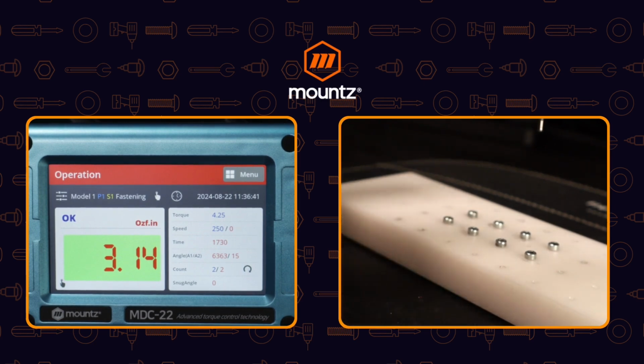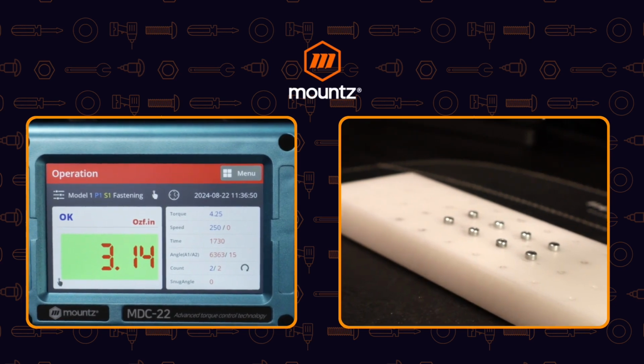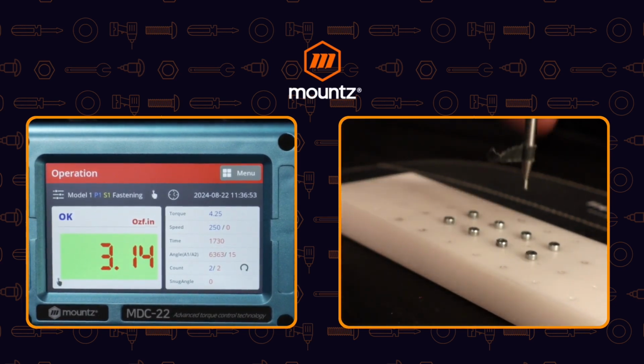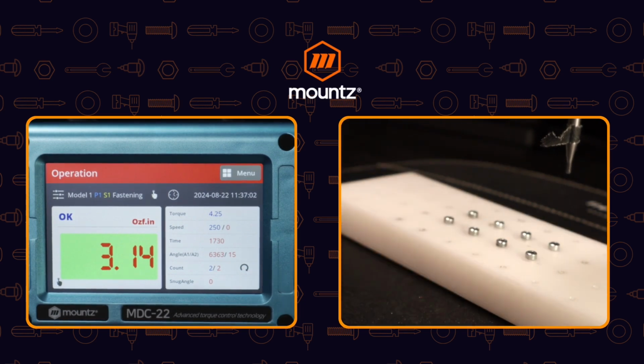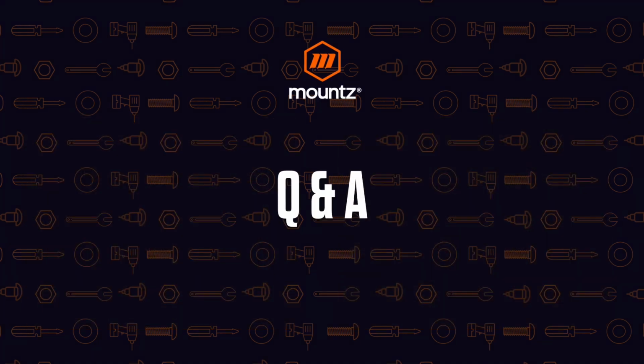We also have, with this torque arm that we are dealing with, the ability, along with another piece of equipment, to make sure that there's only power to the tool in the correct operation area or over the correct fastener that needs to be used. The system will tell it which preset to use, and it will not count that unless it gets a good rundown signal back from the controller. So that's how you can implement different automation types to help satisfy your different workflow operations.